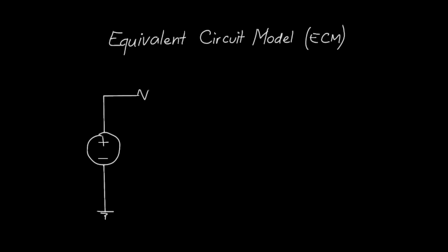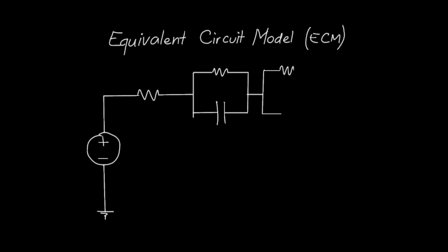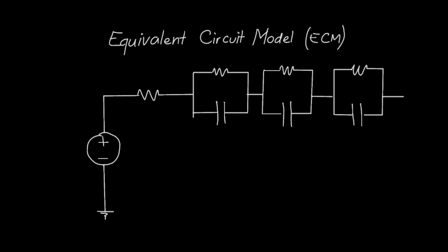It is an electrothermal analog to the battery cell that has a similar response of the cell in terms of current, voltage, and temperature, using an electrical circuit that is much simpler than an electrochemical model. It typically has a voltage source to represent open circuit voltage, typically referred to as OCV, and a collection of resistors and capacitors in series and parallel to represent ohmic, diffusional, and other losses. The topology of the equivalent circuit and its parameters are the fingerprints of a cell chemistry and form factor.